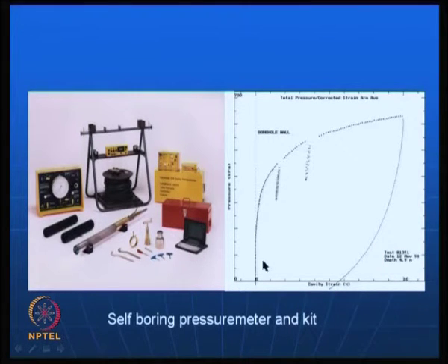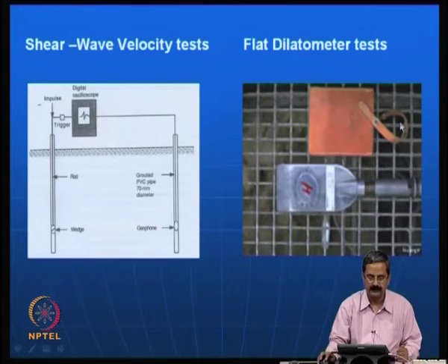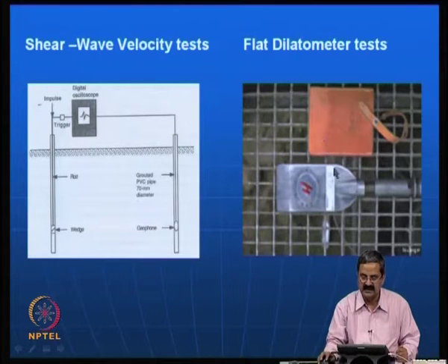This can be used to obtain various properties such as Young's modulus, bearing capacity, settlements, Poisson's ratio, many things. There is a lot of information on this. So, this is a dilatometer I just mentioned, a similar one, where you have a diaphragm here, and then it is a simple kit, actually a very simple equipment. This also has very versatile applications, and shear wave velocity measurements.